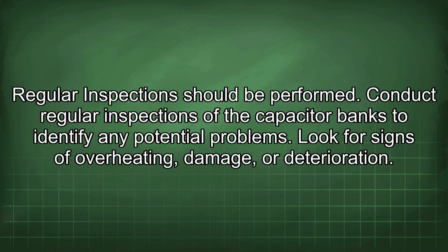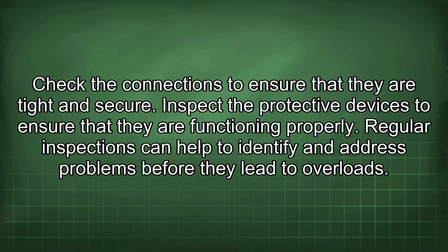Regular inspections should be performed. Conduct regular inspections of the capacitor banks to identify any potential problems. Look for signs of overheating, damage, or deterioration. Check the connections to ensure that they are tight and secure. Inspect the protective devices to ensure that they are functioning properly. Regular inspections can help to identify and address problems before they lead to overloads.